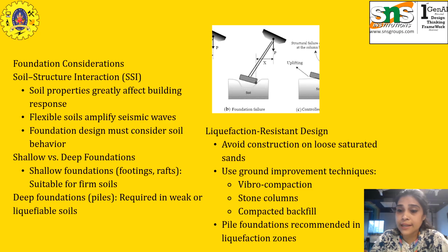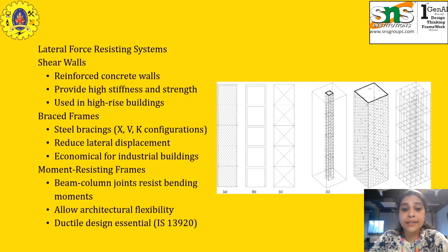Shallow foundations like footings and rafts are suitable for firm soils. Deep foundations like piles are needed for weak or liquefiable soils. Proper foundation choice is very essential in seismic prone areas. Next is designing for liquefaction resistance. Avoid building on loose saturated sands, and prefer pile foundations.